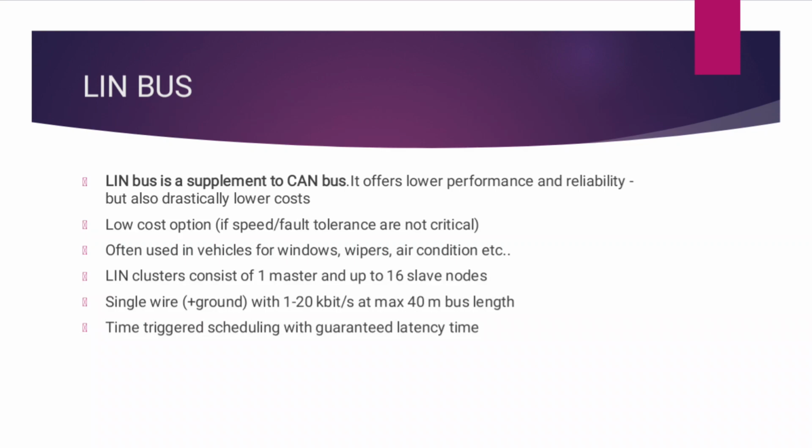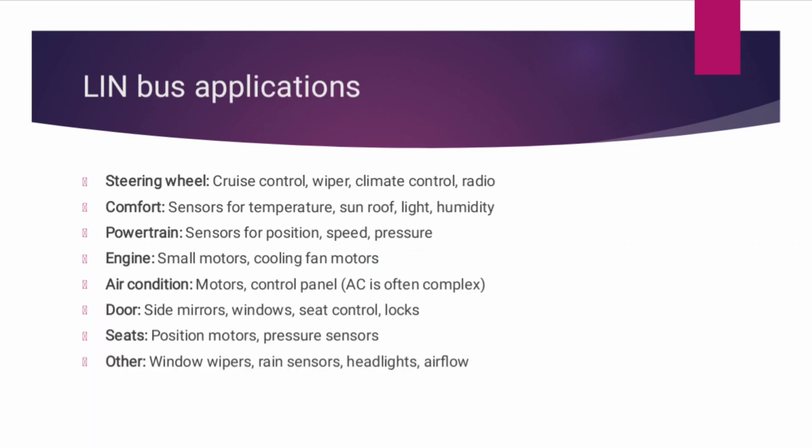LIN clusters consist of one master and up to 16 slave nodes, single wire, time triggered scheduling with guaranteed latency time. LIN bus applications: steering wheels, cruise control, wiper, climate control, radio, comfort sensors for temperature, sun roof, light, humidity, powertrain sensors for position and speed, pressure, engine, small motors, cooling fan motors, air conditioning motors, control panel, doors, side mirrors, windows, seat control, locks, seat position motors, pressure sensors, and others such as window wipers, rain sensors, headlight, airflow.